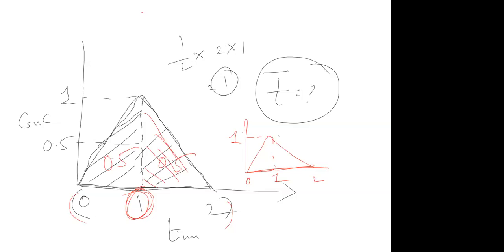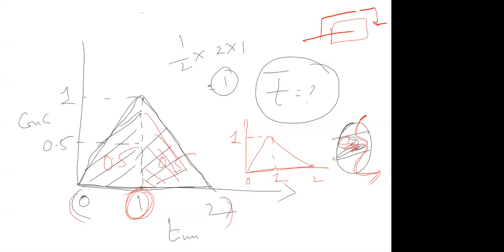Bypass is simple. In a packed bed reactor, catalyst is loaded. Because of some irregular packing, the flow might be bypassing like this. The entire catalyst is on one side, and for some reason the flow is bypassed. Bypass means it is not going through the reactor and goes out. In RTDs we have shown it like this, but in reality bypass means the fluid spends minimum time inside the reactor, because of some malfunction of the reactor. Got it? That is bypass.